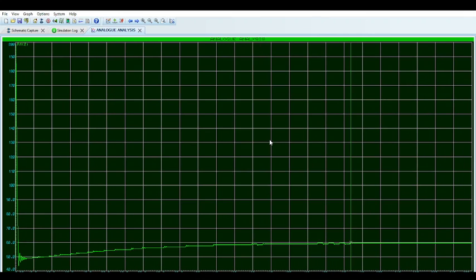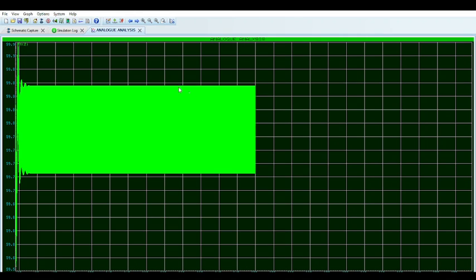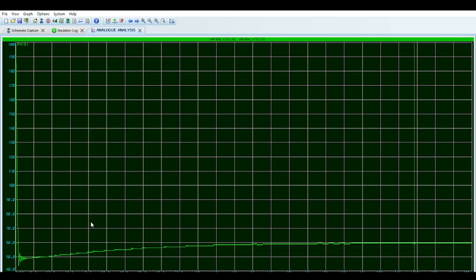So that's 60 volts on the output, and obviously as you can see it's a bit slow. I know it gets to the settling time at 190, but in terms of digital PSUs, that's slow. It should be in the microsecond ranges, to be honest. But in this case, it's safe. You won't even notice this, right?